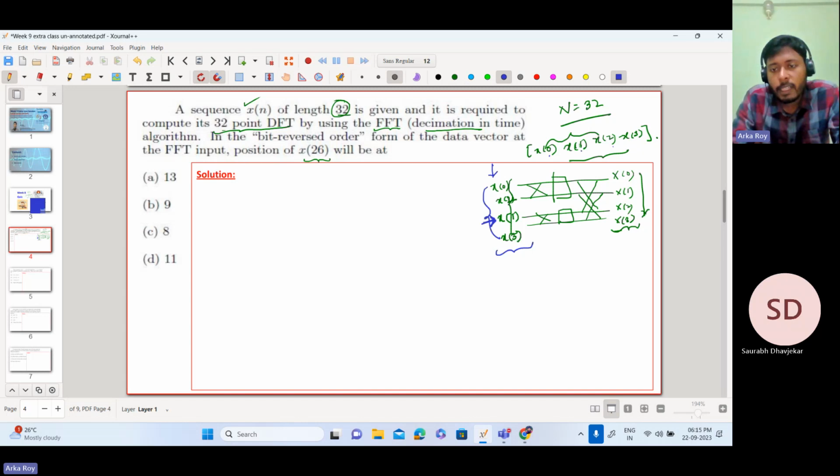Because it is a 4-point DFT, it is very easy to say that I will group the even sequences and odd sequences, and then feed them into the DIT FFT algorithm. However, the problem arises when N increases, for example when you need to compute a 1024-point DFT or 2048-point DFT. For that, it is very problematic to identify at which location each sample will be placed.